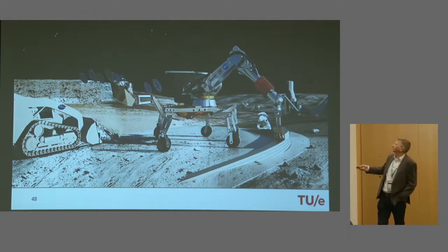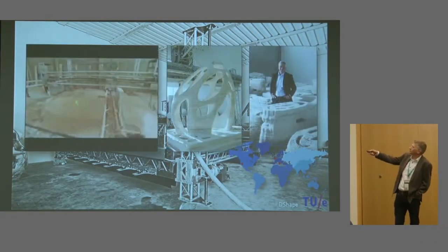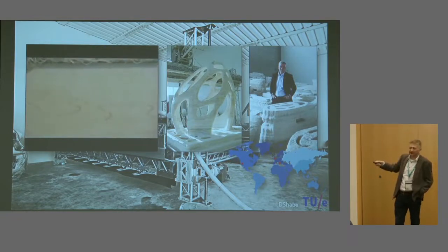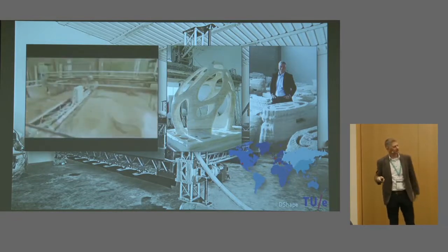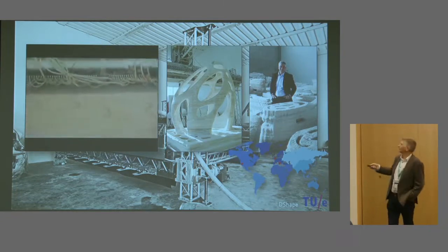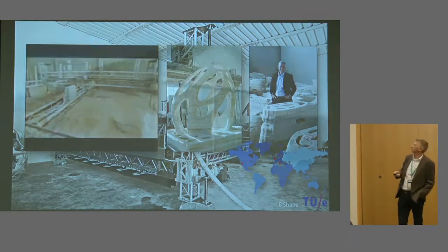The alternative came from Enrico Dini, who had the powder bed technology. There's a powder bed, and then he injected with all the nozzles the binder material, and layer by layer he built up his own model, as you can see in all kinds of industries with powder bed technologies. And if you blow hard at the end, you have a lot of degrees of freedom in your shapes.